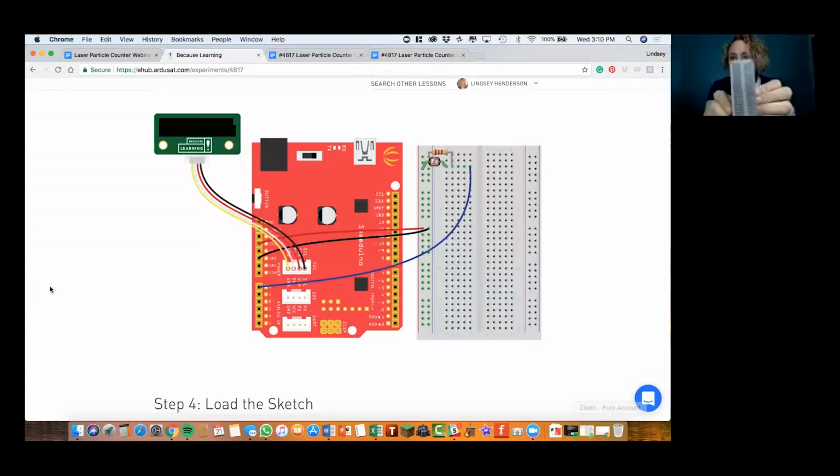On the inside of the breadboard, it's the opposite. All of the holes are connected in rows. So anything you plug into a row will be in your circuit as well. The only exception is there's a little gap right here, and you actually have to bridge from one row to another across the gap. But we're not going to use that in this experiment today. We're only going to use one rail and one side of your breadboard. So columns are connected on the rails, rows are connected on the inside of the breadboard.